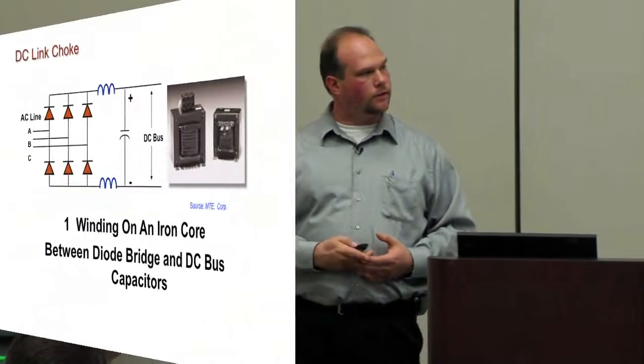What if I put 100 5 horsepowers in there with no DC link chokes? I might want to start looking at that, because now I just put 500 horsepower with a current distortion of 70-some% in my system. I better start looking at my numbers and seeing what that's doing to my overall picture and where I'm at. Start doing some looking at the system.